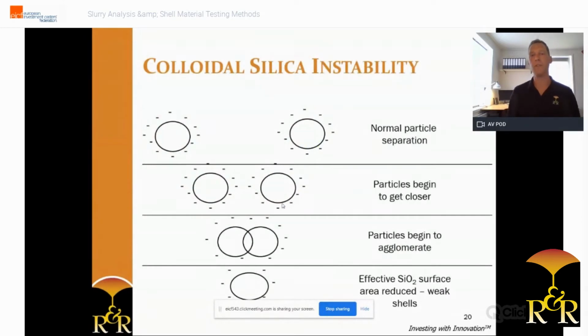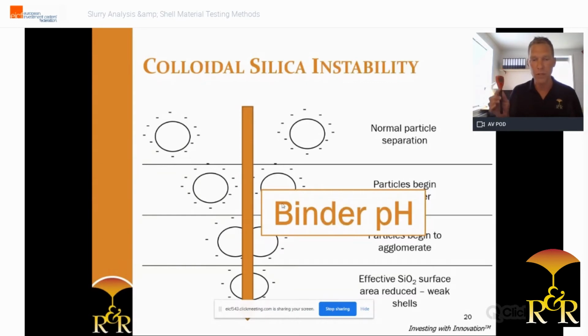So now there is a beautiful aspect that occurs during the destabilization of a colloidal, because while the particles start to agglomerate due to the alteration of the particle charge or the increase of the concentration, the pH is dropping too. So this is making the pH a very important test to perform to control your binder stability.